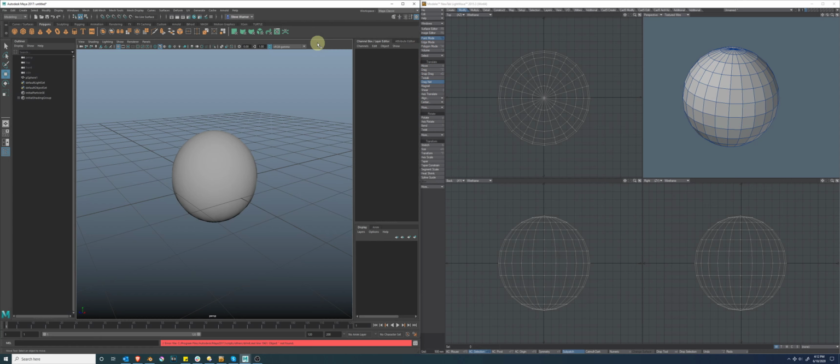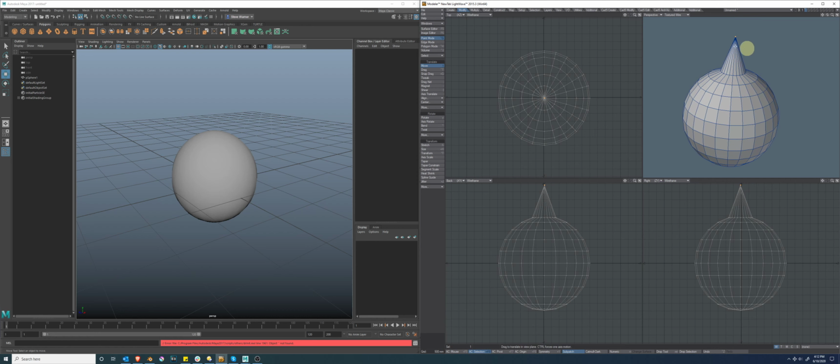All right, welcome back. Today we're going to take a look at soft selection, also called Falloff in some programs, and inside of Blender it's called proportional editing. So what is this? If we are in a program like Lightwave and we select, let's say, this one vertice and we hit move, and then we begin to move up on the y-axis here, you can see that we're only really influencing that one vertice that we actually have selected.